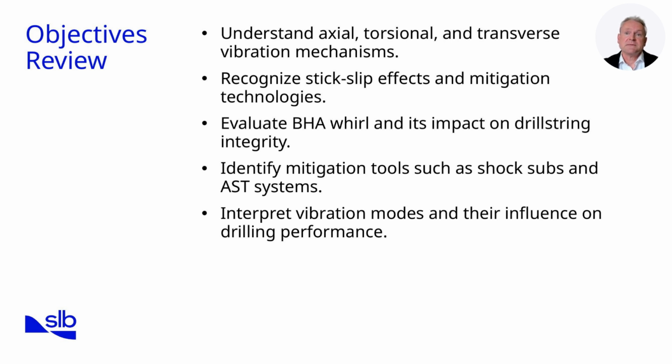Third, we evaluated BHA whirl and its impact on drill string integrity, noting its destructive effects even thousands of feet above the bit. Fourth, we identified mitigation tools such as shock subs and other vibration control technologies, weighing their advantages and limitations. Finally, we interpreted vibration modes and discussed how they influence drilling performance, especially when coupled. Let's now conclude the submodule.